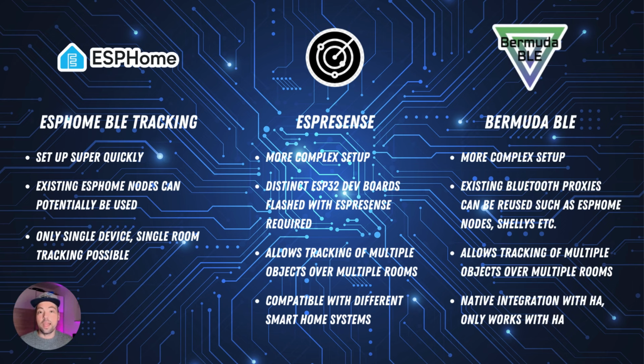The third option I would like to explain is Bermuda BLE. Bermuda BLE works pretty much the same as ESPresense, but the cool thing about Bermuda BLE is that it does not require you to add new distinct ESP32 nodes to track your objects within your house, but you can reuse the existing Bluetooth proxies from Home Assistant. So if you have already some ESPHome nodes in your house that you have marked as Bluetooth proxy, or some Shellys, which is also cool, that work as a Bluetooth proxy.